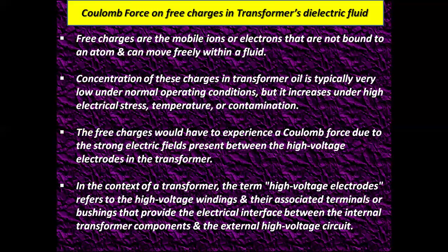Concentration of these charges in transformer oil is typically very low under normal operating conditions, but it increases under high electrical stress, temperature, or contamination. The free charges would have to experience a Coulomb force due to the strong electric fields present between the high voltage electrodes in the transformer.